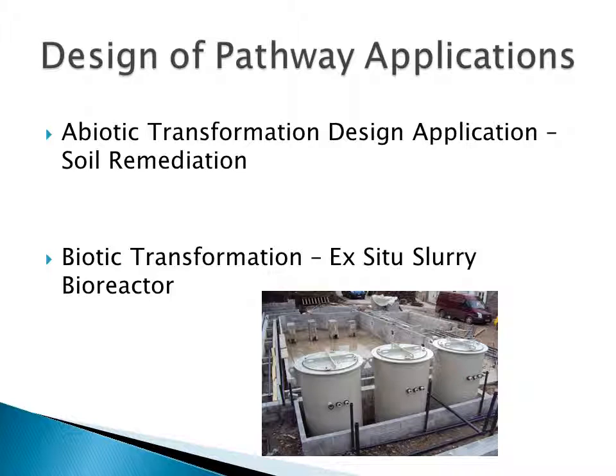A process that has been investigated because of its potential for transport of the oxidizing reagents through soil and groundwater is Fenton's reagent. Fenton's reagent decomposes hydrogen peroxide with transition elements to generate hydroxyl radicals, which react rapidly with many organic contaminants. Many organic compounds can be degraded very efficiently using Fenton's reagent.